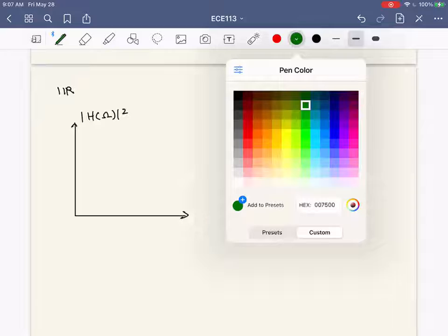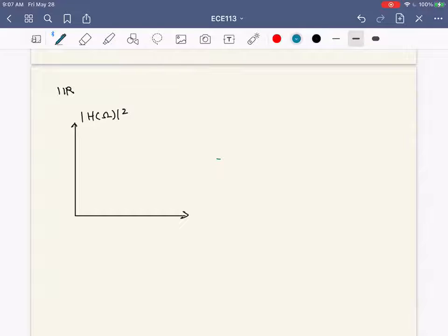And as usual, we still have a general waveform like this. Let me draw it bigger. Okay. But we now normalize the upper bound of the ripple as 1, okay? And the lower bound, now we name it 1 over 1 plus epsilon square, okay?